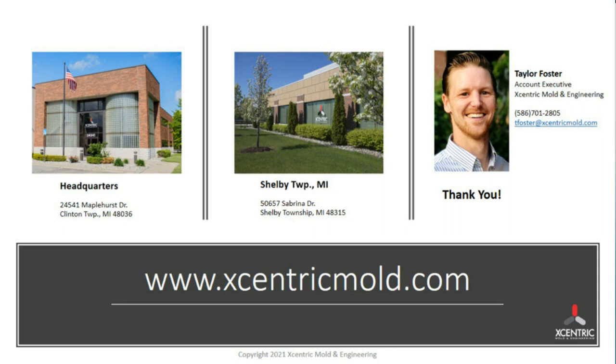One note is there are prototype toolers out there who do offer a lifetime guarantee on their aluminum tooling, with the intent to be a longer-term resource, right? Be able to hold people over in between prototyping and production in an area we call bridge tooling, which is where you still need products, but your production tooling takes months to create. So it's nice to have that aluminum tool or that prototype tool continue to make parts for you in that interim, which is why a lot of prototype toolers, or some of them out there, we're one of them, would offer a lifetime guarantee on the mold, so you can get beyond that 10 to 25,000 parts you could expect. Very good question.